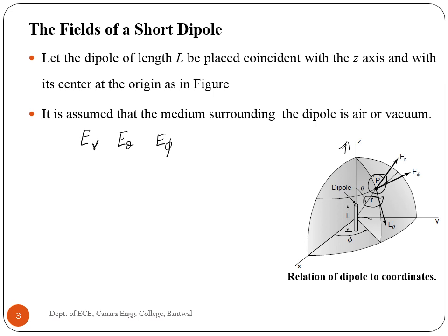Instead of writing the current I, the current along the dipole is I0 e^(jωt), which implies instantaneous propagation of the effect of the current. The propagation time is accounted for as done by Lorentz, and we can write I = I0 e^(jω(t - r/c)).